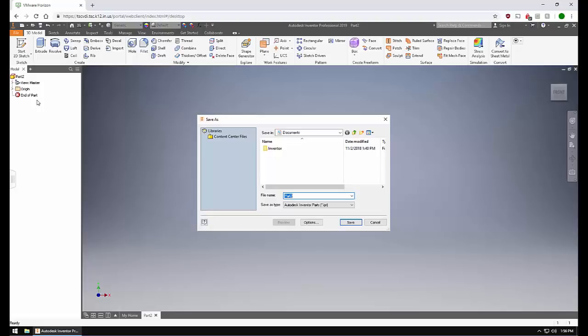Click on the downward arrow in the pop-up to view different locations to save your file. Select the location that has your username, followed by some gibberish, and ends with a letter. In my case, the letter it ends with is an H. In the box next to File Name, rename your file to a unique name. Make sure you name your file in such a way that you know what your part is just by looking at the name. For instance, if you made shape 1, name your part shape 1.